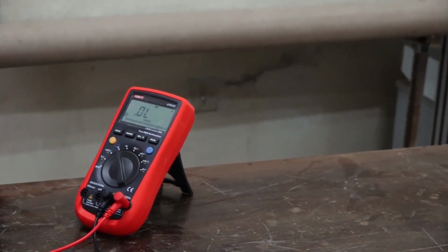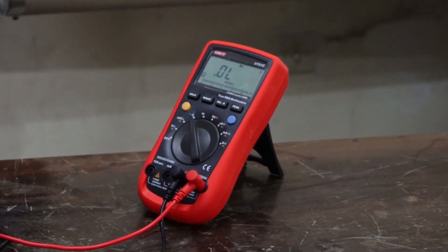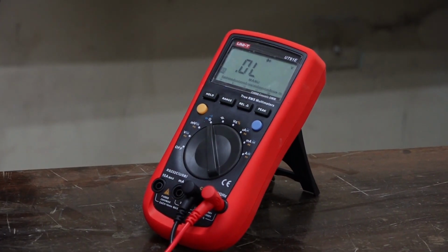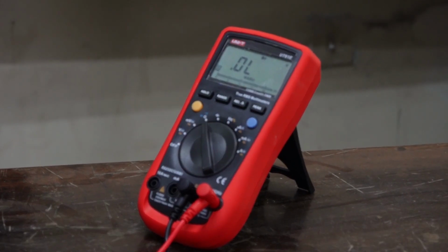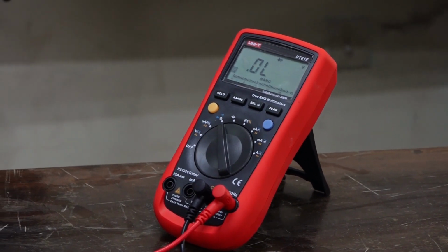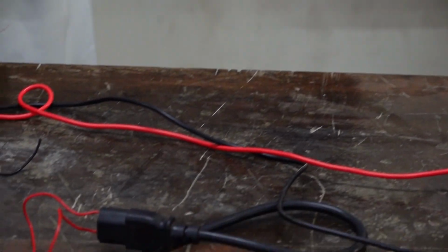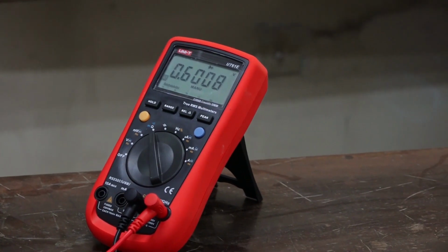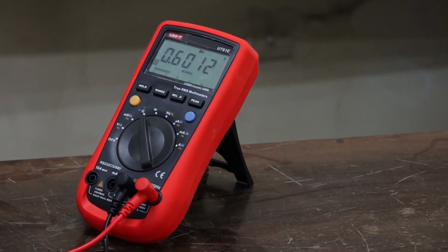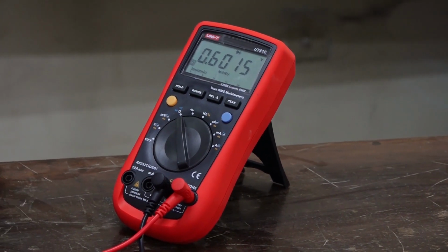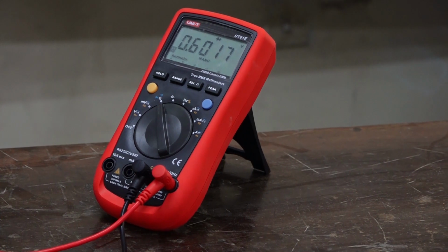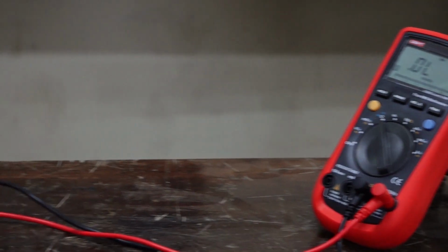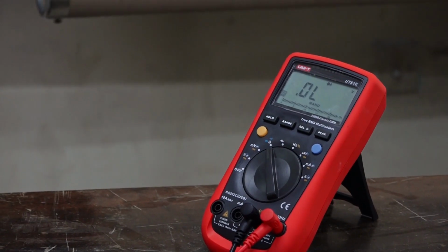That's why I told you that you need a multimeter for your experiment. Or sometimes if you find a challenge, you can just use the breadboard to do your measurements. You just connect them without taking care. So now the potential barrier is 0.600. What do you see there? 0.6015. So that diode is active. It's working. If you reverse, what will you see? OL means over limit.